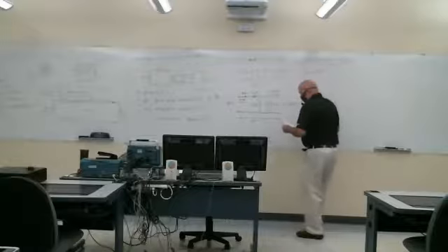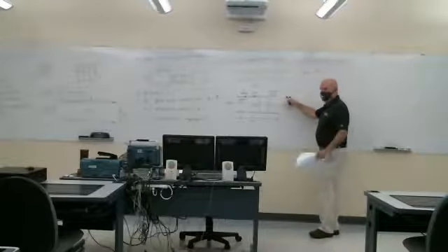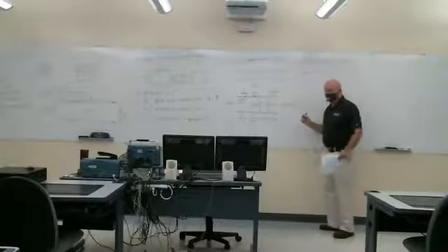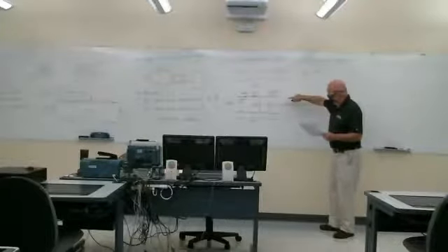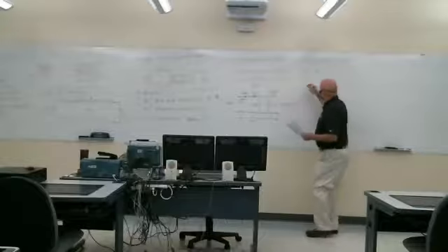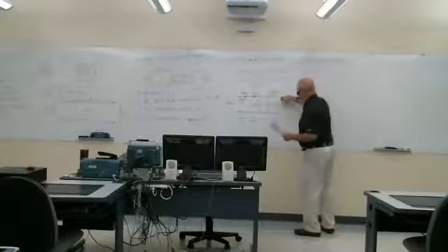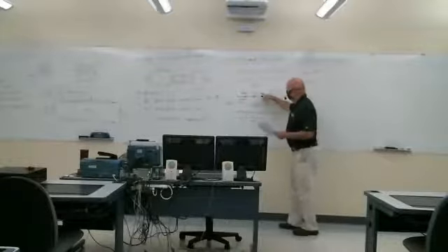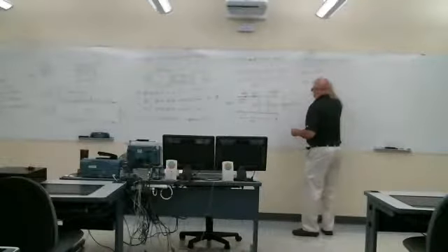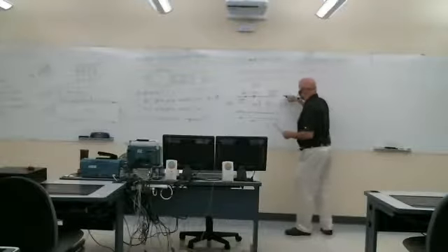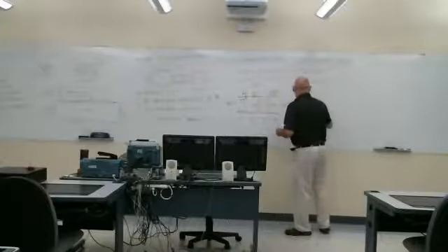So from Kirchhoff's voltage law, I'm going to start right here at this point. Normally I go clockwise doing these Kirchhoff's voltage law things, and we'll go clockwise, but we'll start here. So it's plus V(z + delta z, t), starting here at this point. And then we're going to go clockwise around this outer loop. We get minus V(z, t), and then here for the resistor, I get an IR drop.